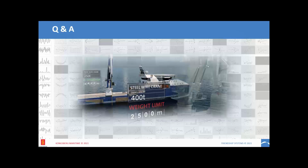That would then leave me with a number of designs that have completely different hydrostatic characteristics. And then I could use constraints during my optimization procedure and say I want to limit my feasible design space to longitudinal center of buoyancy between, I don't know, 49 and 49.5% of the length of the ship or something like that. So yeah, definitely, they can be loosened. Thank you.